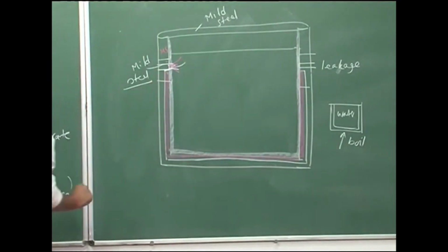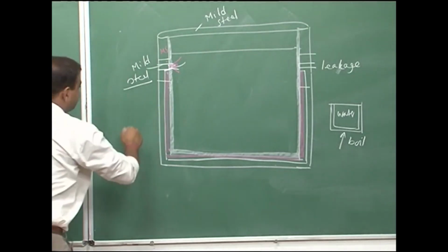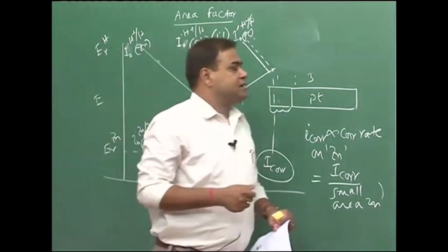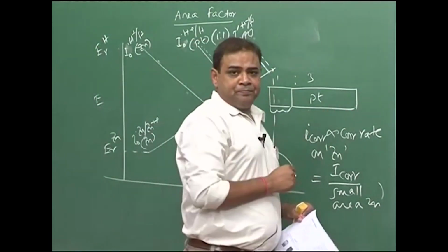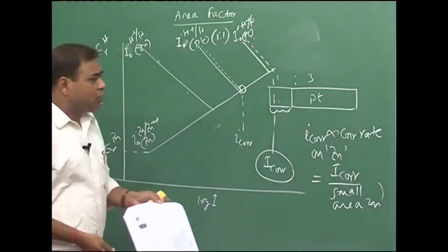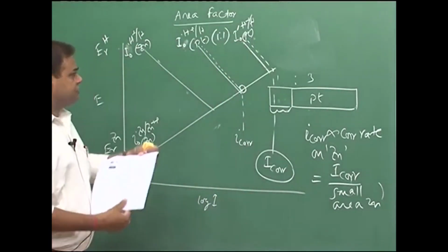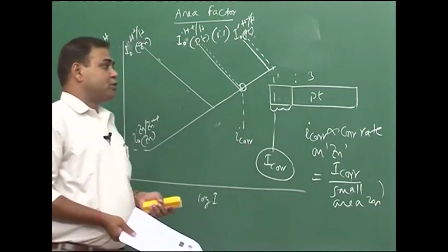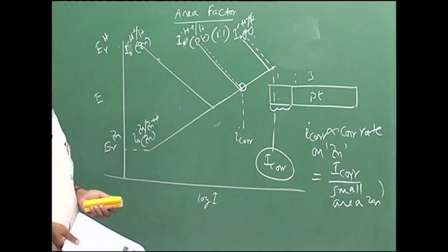So, there are three examples we have discussed, and in case of unfavorable area ratios, the corrosion rate of the anodic zone would be very high, and then finally, there could be failure in a very short duration. Now, we see that galvanic corrosion is definitely bad and we have to control it, we have to protect the system from galvanic corrosion.